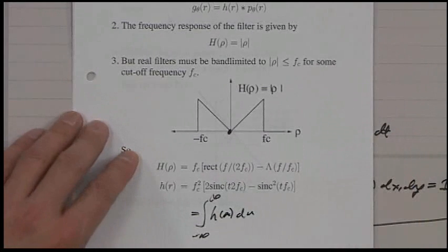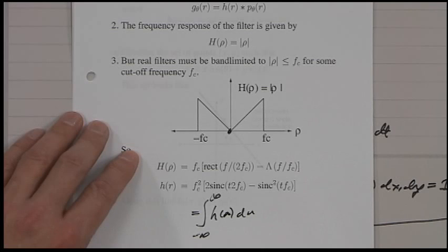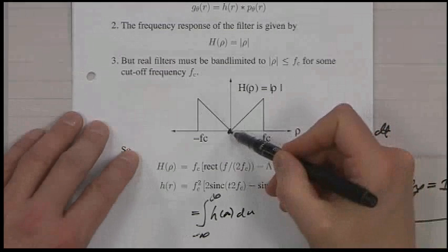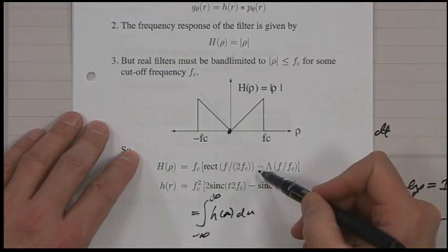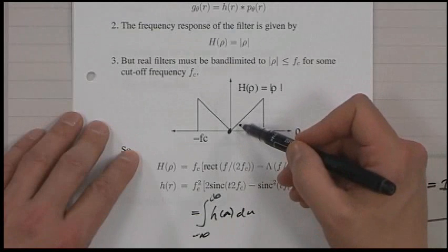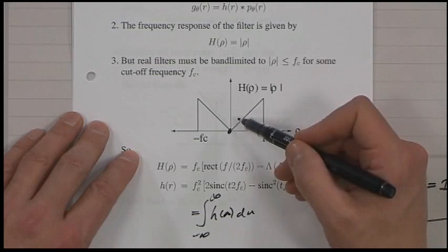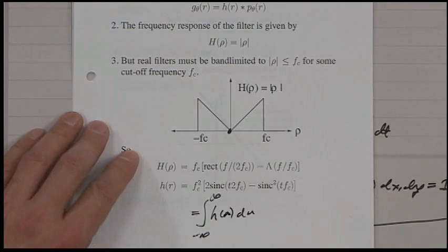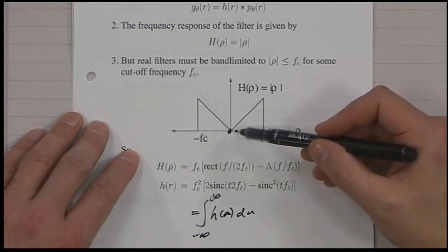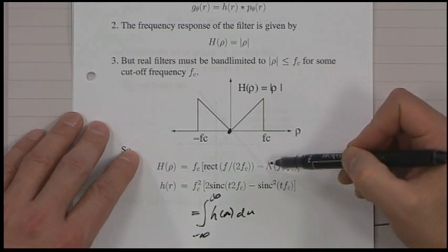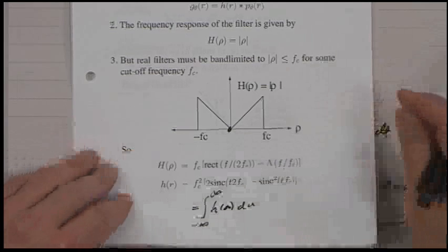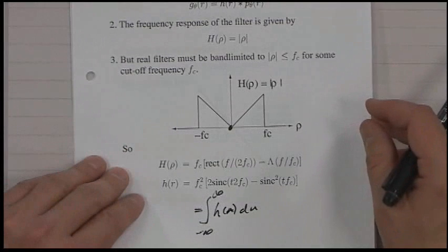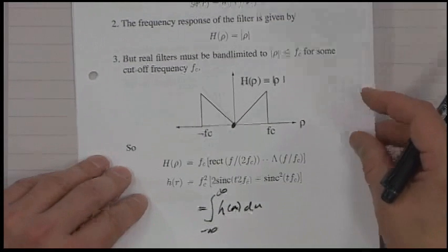You should be able to go back and forth and say quickly, oh, okay, well, the filter's gain is 0 at DC. The area of this is 0, or if it's 1, this is 1. Usually in filters you apply to images, their gain is 1. So there's an interesting paradox here, which is that the gain of the filter at 0 is 0, but the reconstructions you get are all strictly positive. How's that possible? I'll let you ponder that, okay? It's an amazing paradox of filtered back projection, but it's true.